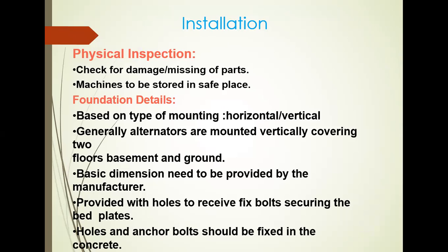Then after that, the main important topic is foundation and installation of the synchronous machine. So first, physical inspection is needed. First, the area selection is needed. There we have to check for damage and missing parts, and the machine is to be stored in a safe place. That physical inspection is mainly needed.